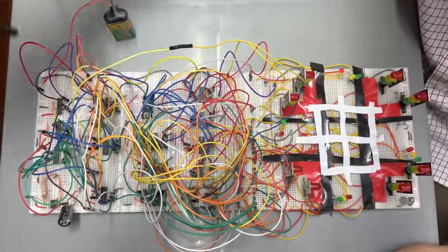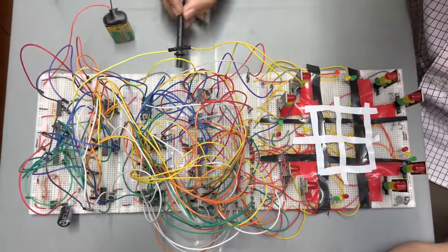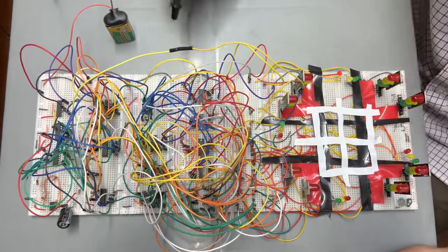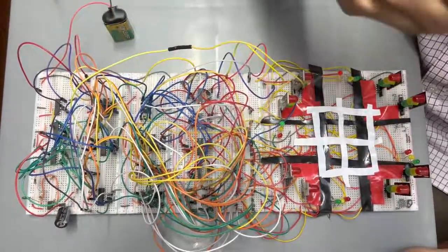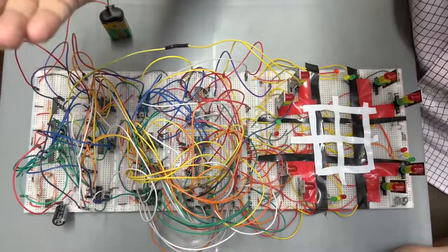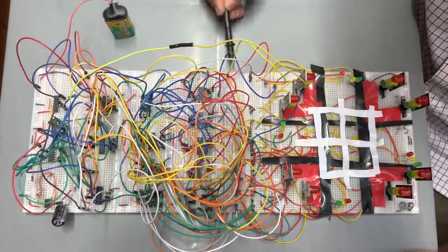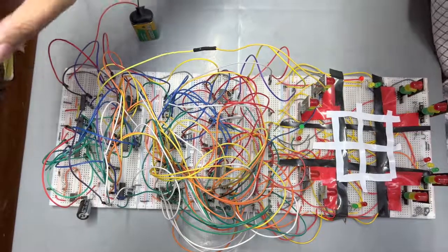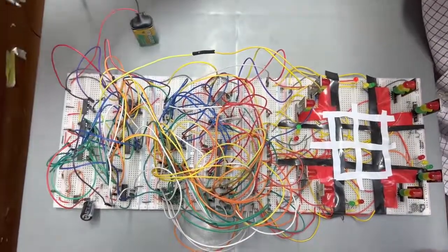Afterwards, all of these signals have been fed to some universal gates. These basic gates have been used to implement all of those periods, which will be used in our traffic control system, which has been previously presented in our software simulations. All of the basic gate implementation can be seen in the middle three breadboards, and in the initial breadboard here we have implemented the 555 timer IC along with the 4017 ring counters.